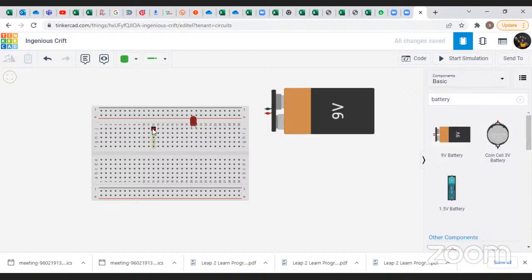Now on the breadboard, I hope you all know about breadboards. On the breadboard, the upper rows are negative. This whole line is internally connected, and this one also internally. These are different; these are not connected internally. This minus and plus, individually, these are internally connected. These are all volts, and this one also.